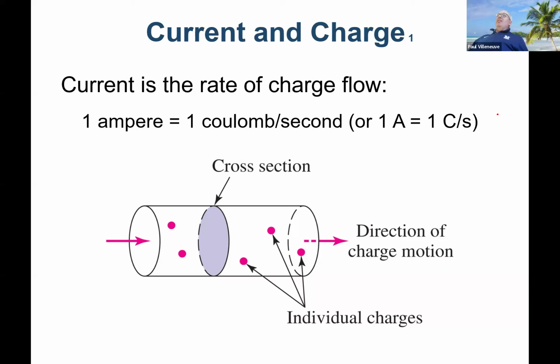So inside of a switchgear, you'll try to limit the amount of space that you have, and so copper bus bars usually tend to be rectangular for space savings. Also, with switchgear, most of the time you're talking medium voltage, 15 kV or less, and you're not talking 345 kV. You can if it's GIS. But for the most part, you're talking medium voltage stuff if it's solid dielectrically insulated.